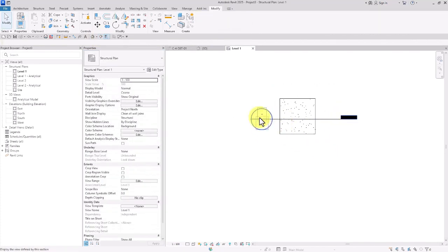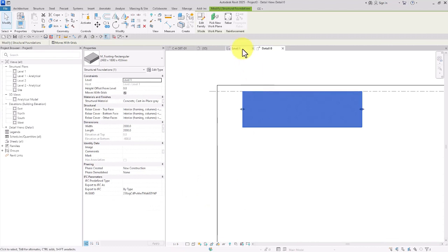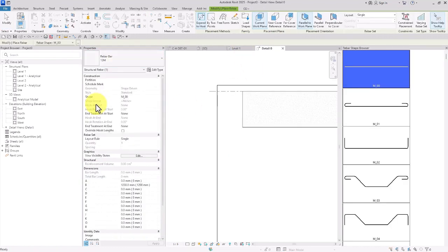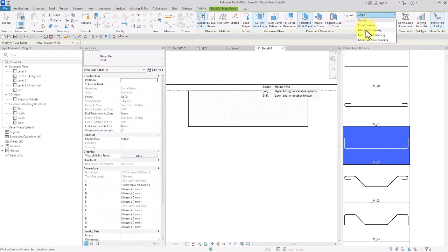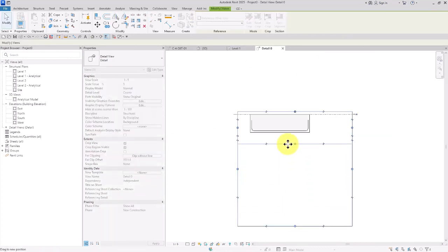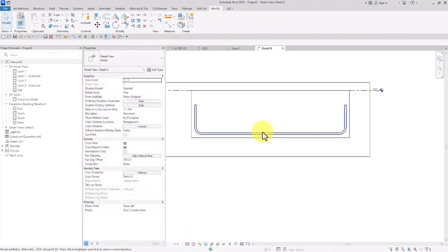And then enter the section. Now, I want to set a rebar here. For its diameter, I'm going to go with 22 again, and with any number that we want. For their gap, I'm going to go with 300, and we can set them here. Reduce the size here, and set this on fine.